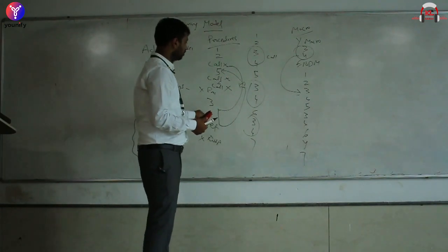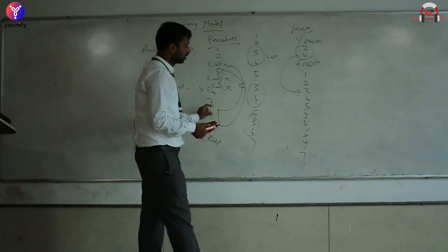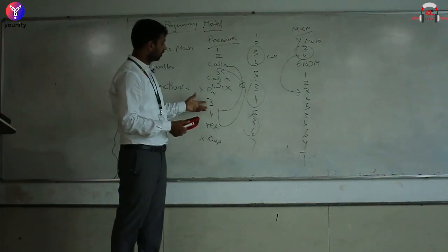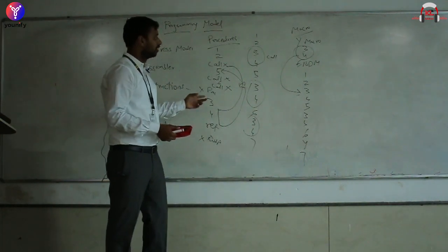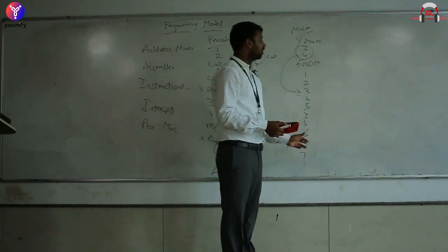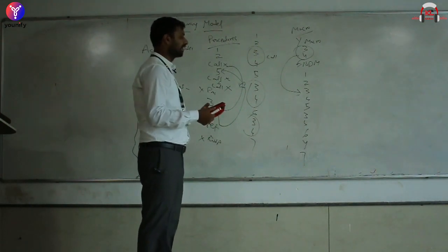We usually prefer procedures. But if the repeated lines of code are few, maybe these 2 lines, instead of running 3 and a couple of lines, making 3 pushes and 3 different pops, we can simply use a macro which will actually replace the code. Where is the code footprint getting affected? Footprint is the size of the code.